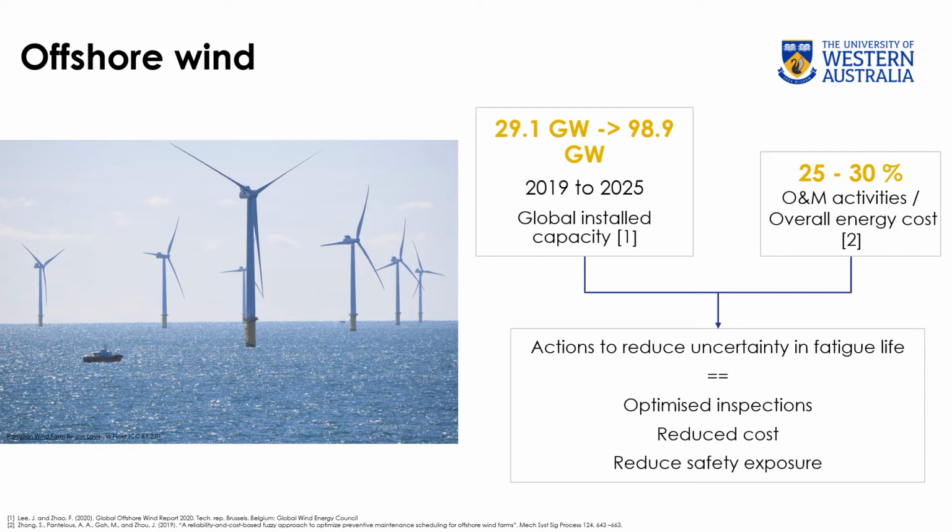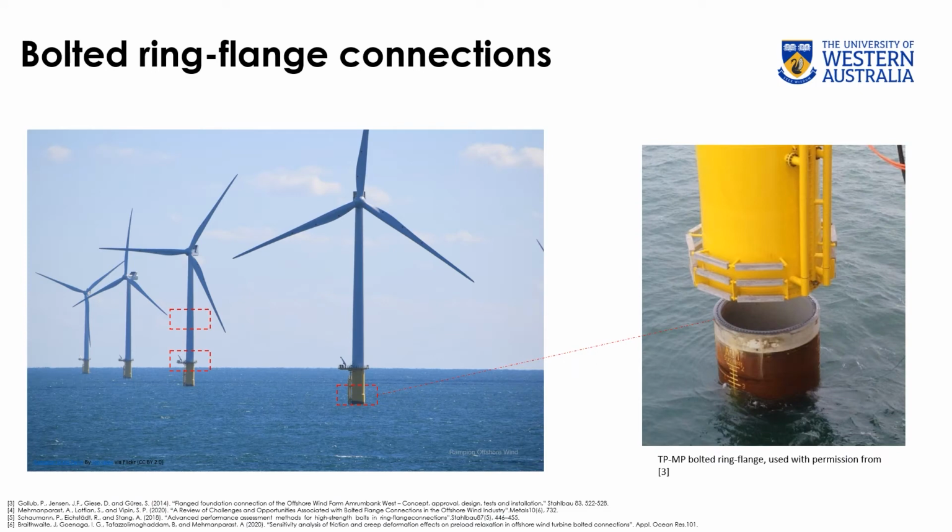In this paper, we are interested in the opportunities in fatigue life assessment of the structure and managing uncertainty in fatigue. We are particularly interested in the fatigue assessment of bolted ring-flange connections in the offshore wind turbine structure. On the left, a basic breakdown of some locations in the structure where major bolted ring-flange connections are located. Increasingly, the connection between the monopile foundation and transition piece, see on the right, is being made with bolted ring-flanges. See Melinda's paper from 2020 for context on this uptake.